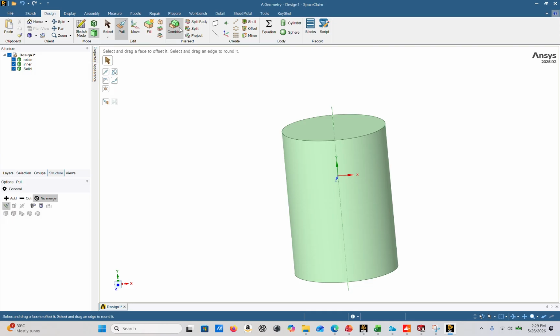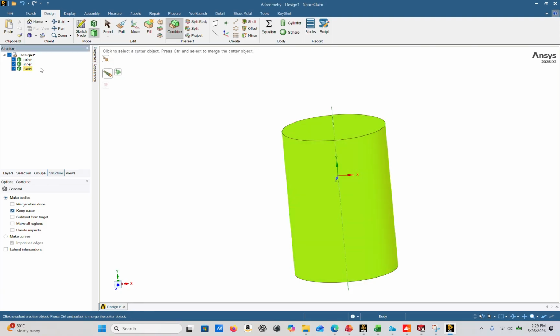Now we need to make sure that the outer, which we haven't renamed yet, the solid is removed, the inner is removed from the solid. So let's do this by selecting the solid, and we're cutting the inner. And again, we're gonna make sure we select the right solid. It might be kind of confusing because there are now 3 solids because you're cutting other things, and you want to make sure that the pink one is the one that we want.